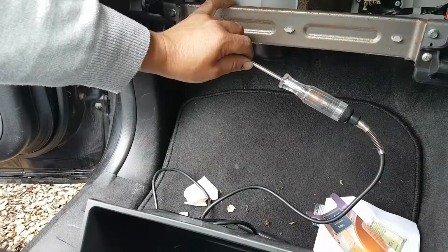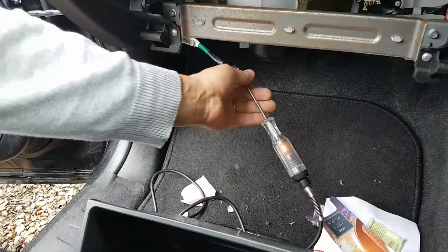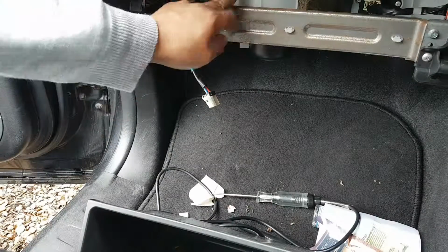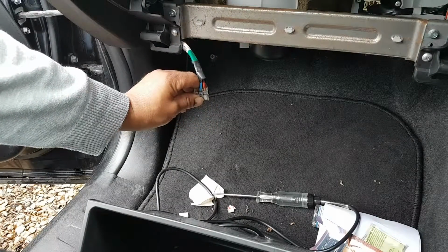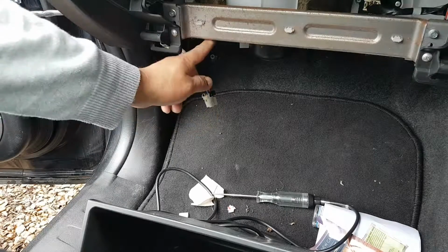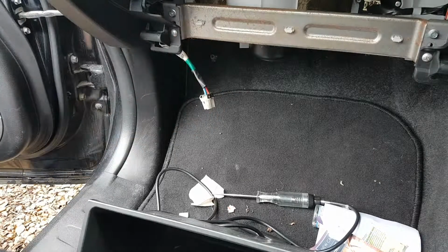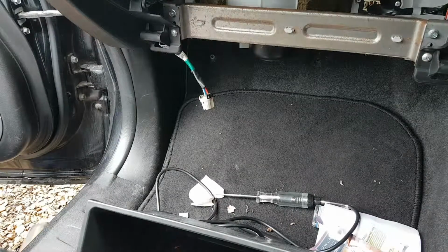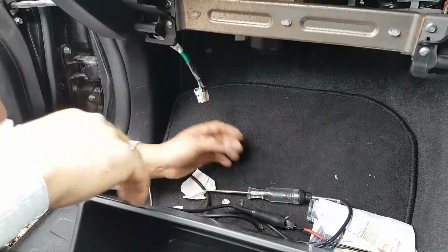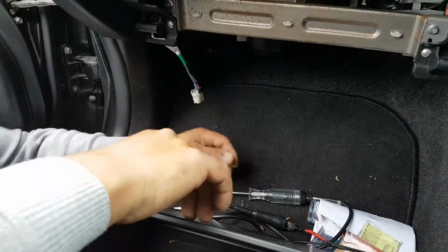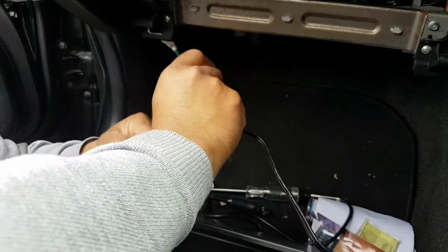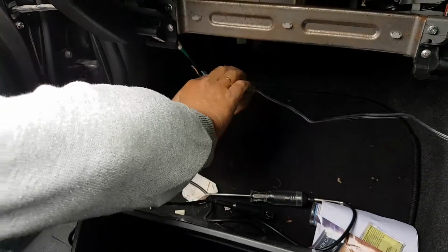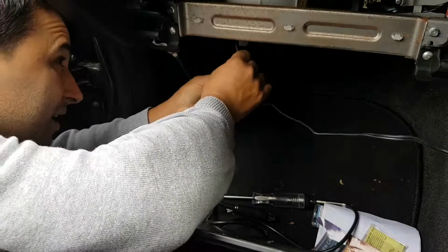Now what I need to make sure is I need to load the positive side, make sure I actually have 12 volts here, and at the moment looks like my fan. But what we're going to do as well is test the fan, maybe just back probing there and just apply voltage to it, see if it runs, and go from there really. So actually I can do that now, I guess. Yeah, I can use this from the cigarette lighter. It should be enough. It goes like that, which means my ground is on that side. Is that long enough? Yeah, it should be.